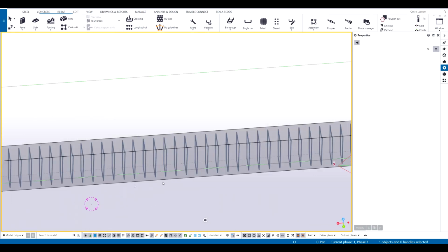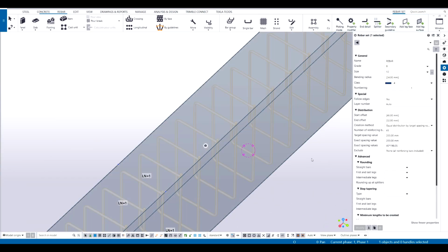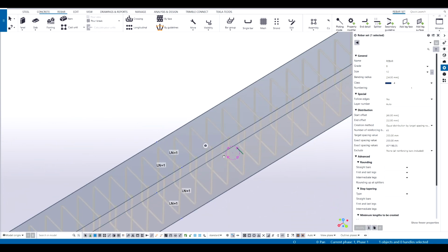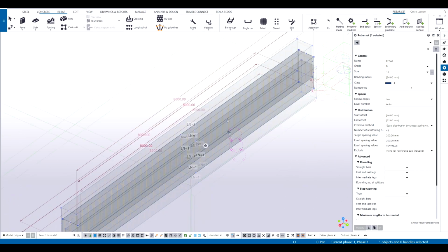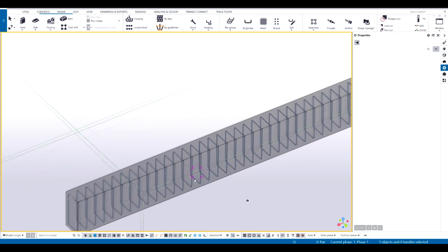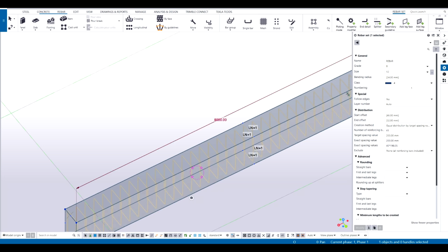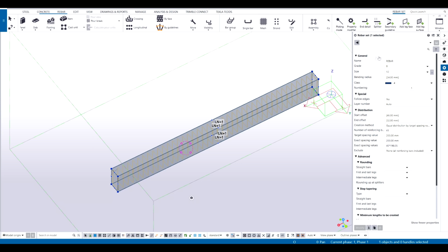Now you would be saying who's gonna be using this kind of a link? It's kind of useless. You might wanna be putting a shape code, say a 51 or 52 link with hooks over here. So in a minute I'll show you how to do that. So you'd select this. Now you'll see another rebar set little thing appear over here. So there's multiple things. Property modifier. Anything that you see here is a property of this rebar set.